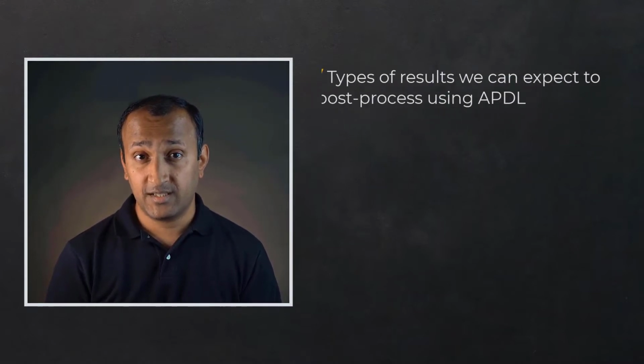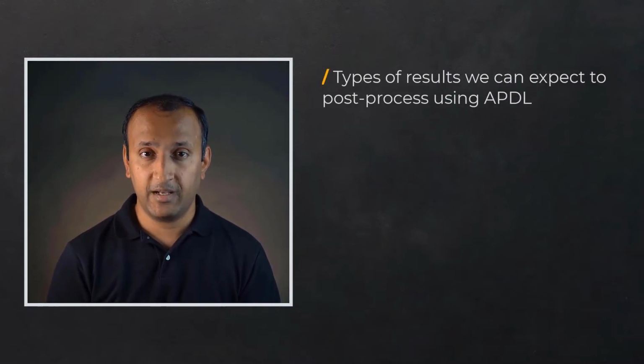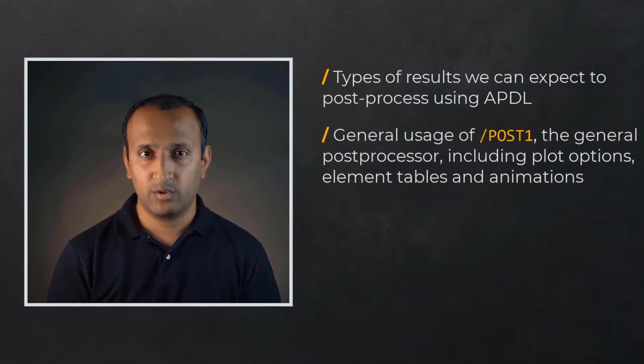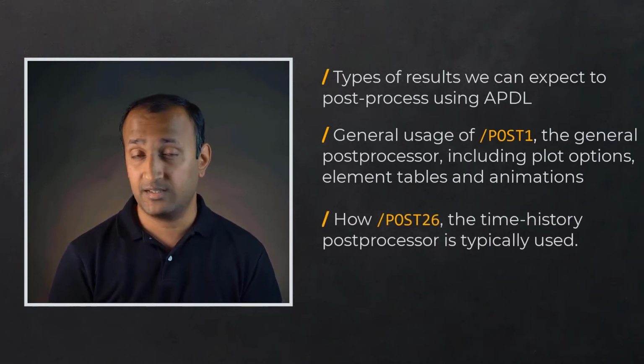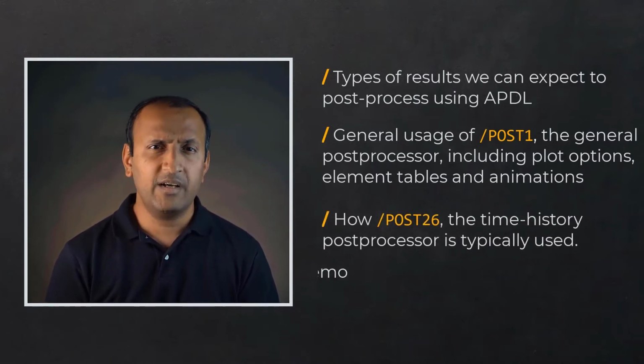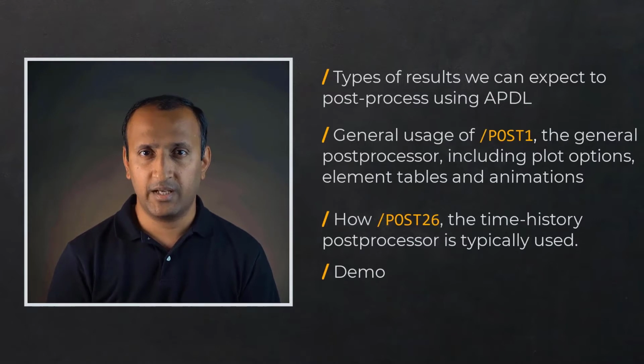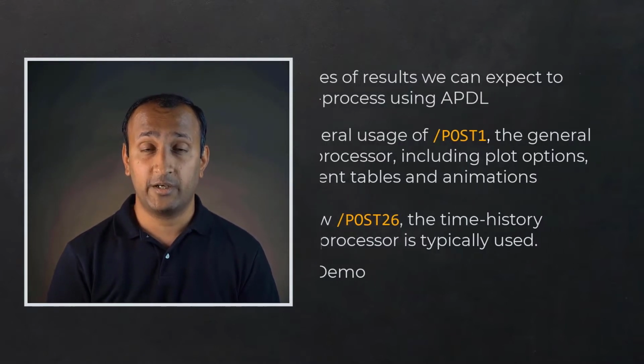In this video, we will discuss types of results that we can post process using APDL, general usage of POST1, including plot options, element tables, and animations, how POST26 is typically used, and we'll demonstrate some of these concepts using a structural analysis of a simple ball grid array model subjected to thermal loads. Let's get started.